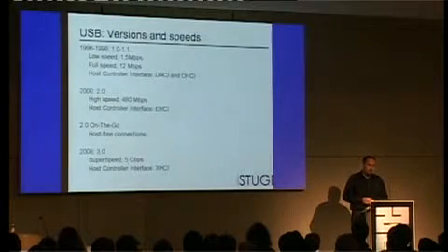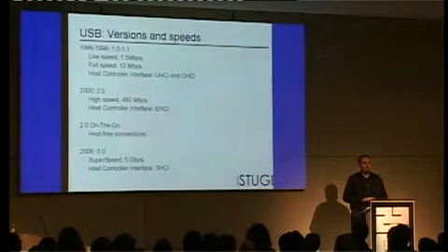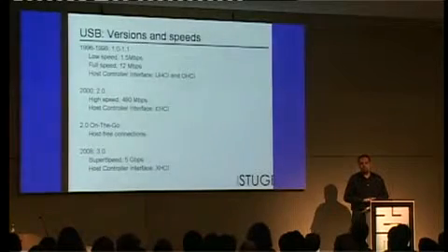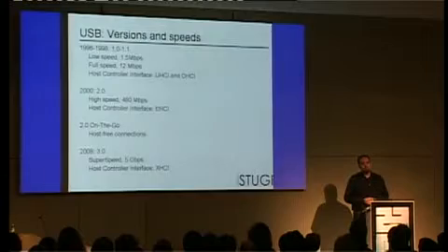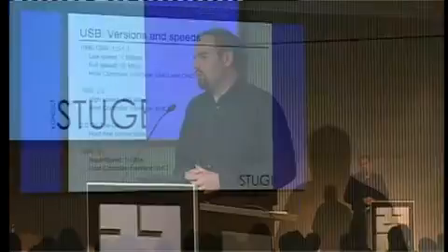And also around the time of USB 2.0, there was the EHCI host controller specification. So USB 2.0 host chips are all programmed exactly the same way, so we only need a single driver for that. That's nice, as long as they adhere to EHCI, that is. But most do, so that's good.